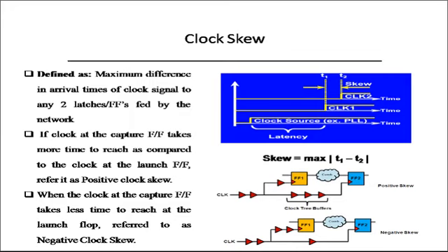If the clock at the capture flip-flop takes more time, then definitely, as I initially explained, for flip-flop 2 the clock will take more time. As the delay is more, definitely flip-flop 2 is a capture flip-flop in this case.